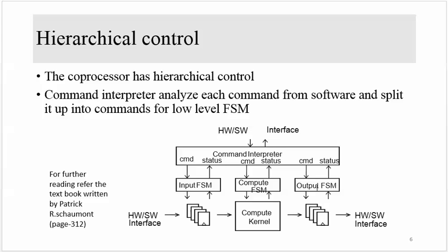The method of using a start-done pulse is insufficient when working with pipelined submodules. If you have submodules that have a pipeline, then this way of working is insufficient, since a done pulse only appears after the pipeline latency of the submodules.